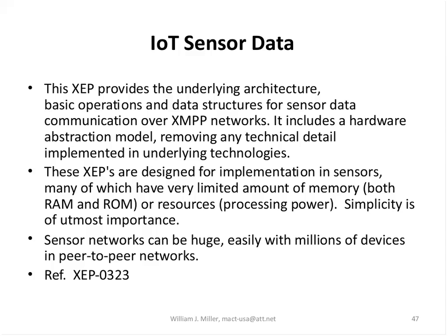You know, the simplicity is of utmost importance, because we're looking at dealing with literally millions of devices in the Internet of Things. And today, when we would do such things for provisioning access to information, we, in many cases, don't actually even send a tag name. We may just send a data slot from a register, if we were using Modbus, for example. The endpoint has to remember what the tag is for that information and the description of that information. That information has to be shared with other people.